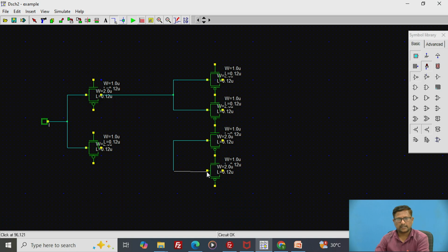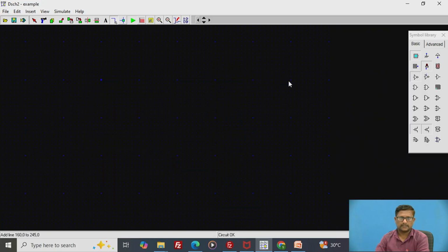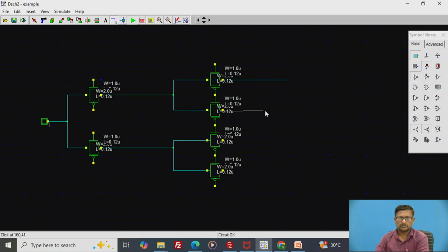So you can connect now according to the diagram, according to the layout you designed. Now we can connect these output lines to the LEDs. So you can drag the 4 output lines Y0, Y1, Y2, Y3, where we are going to connect the LEDs at each output line so that we can get the result.